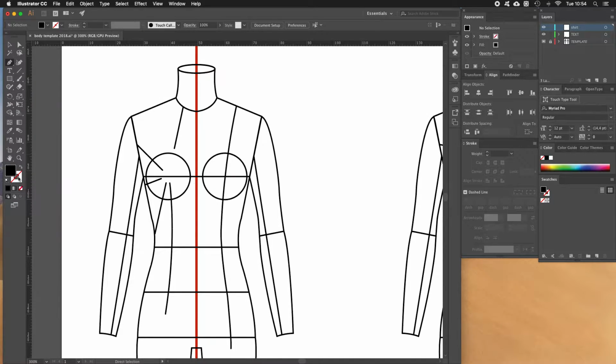So how do we swap the colors from my fill to my stroke? Well, I could either click on swap, this little arrow over here, or I can create no fill, no color for my fill as well. So you can see if I press my little swap button, it just swaps both around. So I want no fill, and I want a specific color in stroke. Because the outlines of this template are already in black, I want to change the color of my stroke so that I can actually see what I'm designing.